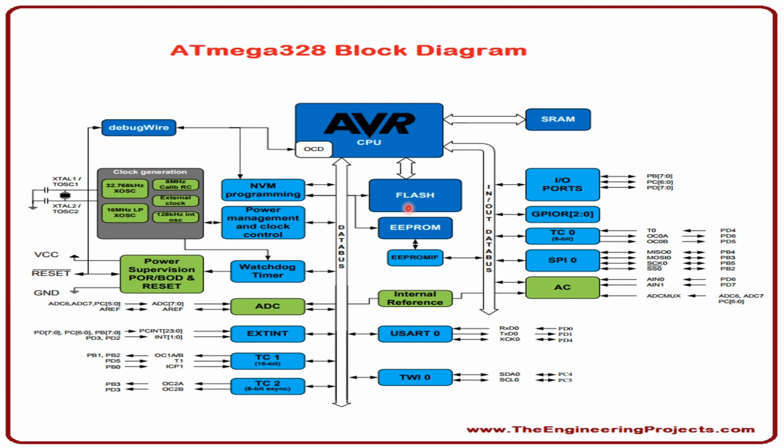So again, like I mentioned before, bootloader. So what is a bootloader? A bootloader is generally a set of instructions for a microcontroller. Basically, when we start the microcontroller, there are some instructions for that microcontroller to begin with. That is a very important program, and we have to flash the bootloader first before operating or uploading any program onto the microcontroller. Okay, but Arduino does all that job for you as well.